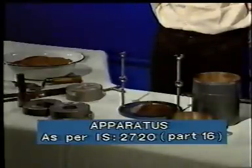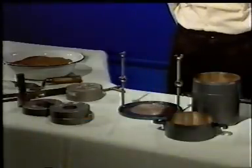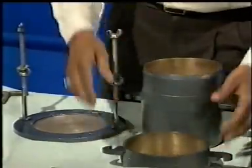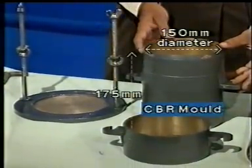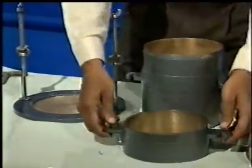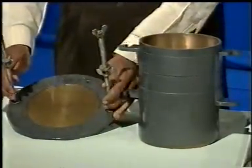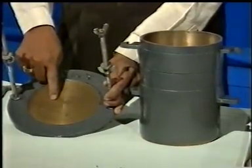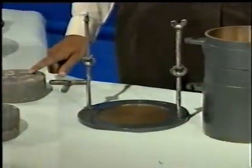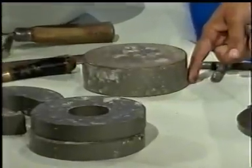The apparatus as per IS 2720 part 16 comprises a mold with internal diameter 150 mm and a height of 175 mm with a detachable collar, a detachable base plate having perforations at the bottom, a spacer disc of 148 mm diameter and a height of 47.7 millimeters.